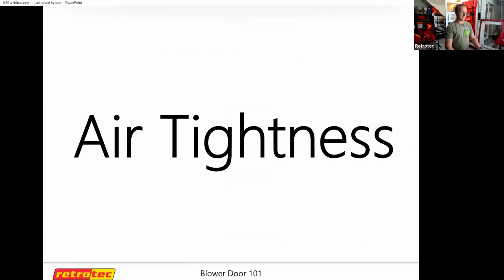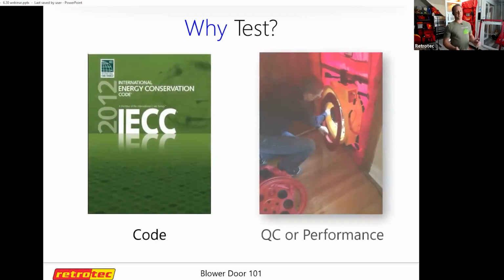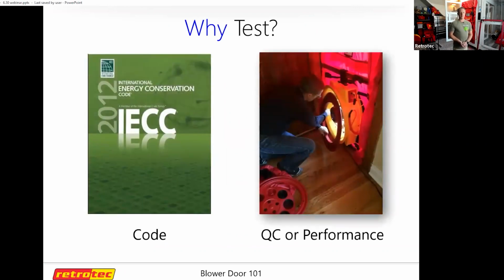So, air tightness testing. The reason why we run these tests, there's several different trades that get into this. The first one that comes to mind for a lot of people is energy auditors. If you're going to do an energy audit, you need to know the air tightness of the building. However, insulators get into this too, because not only do they insulate buildings, they also do a lot of the air sealing that's required. If they're coming into an existing building to do some weatherization work, they'll run an air tightness test, do the air sealing, and then run a post test to see how much it dropped and maybe see if there are some spots that they missed that they need to go back and cover.